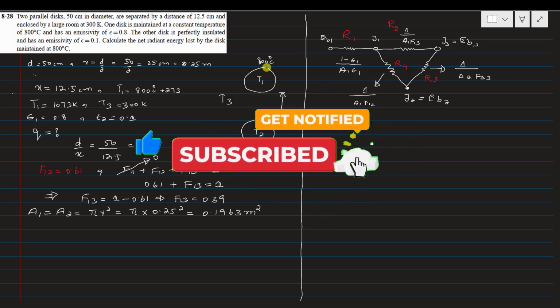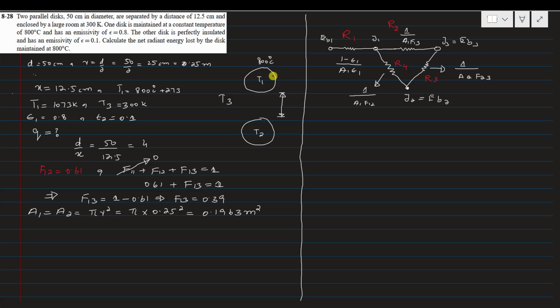So these are the resistances R1, R2, R3, R4 that will be offered to the heat lost by this disk that is at 800 centigrade, and the heat lost from this disk will be transferred to the second disk and the environment, the room temperature, that is a very large area. So that's why its surface resistance is considered 0, and that's why J3 is equal to EB3.